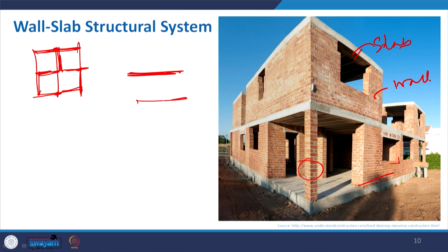But sometimes you have the longer sides, the wall thickness, which are essentially carrying the load, and then maybe there are some internal partitions to create interior space which are not load bearing. So, whatever the slab is resting on will basically be these two walls.